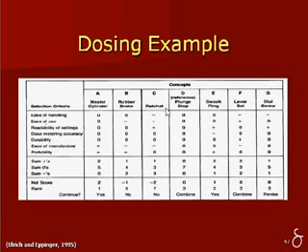Seeing is believing here, so what we do relative to the plunge stop, if we look at the number of pluses and the number of minuses, and we subtract the minuses from the pluses, so 2 minus 0 is 2. That's the net score. Clearly the reference is going to have a net score of 0. It's going to be all zeros here, 7 zeros for 7 requirements. And it turns out if we look at the net score for each of the 7 concepts here, you see that the highest number is 2. So that's something we want to move forward with.